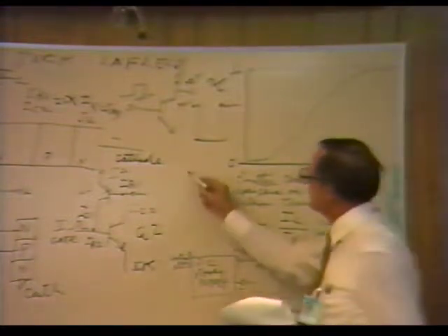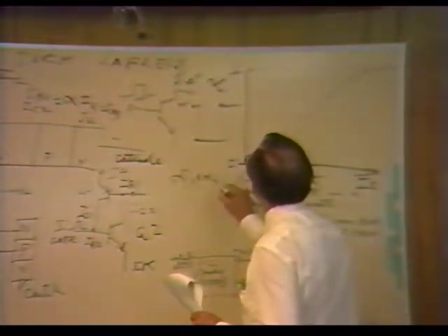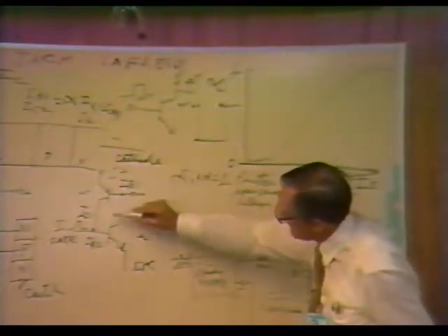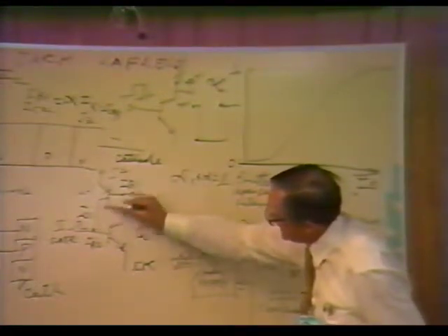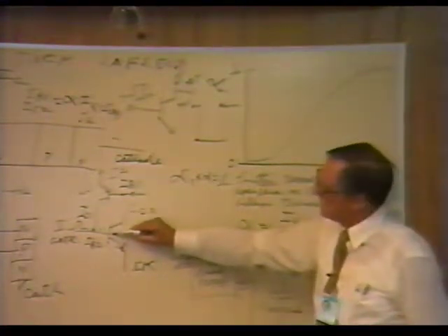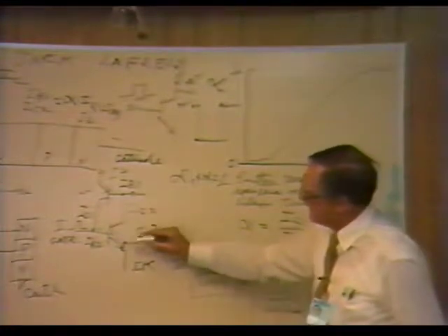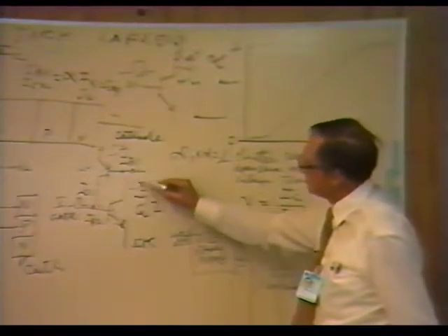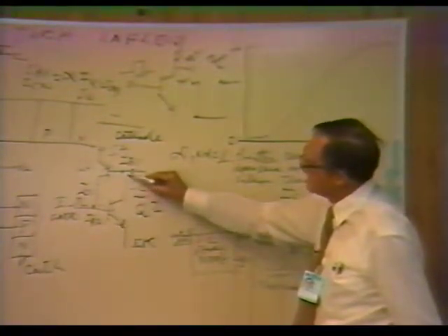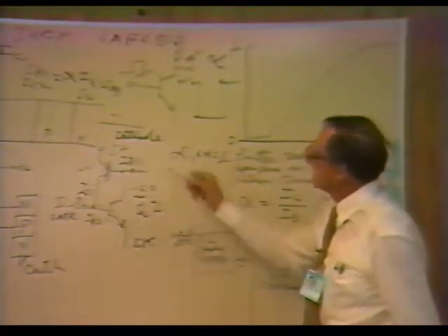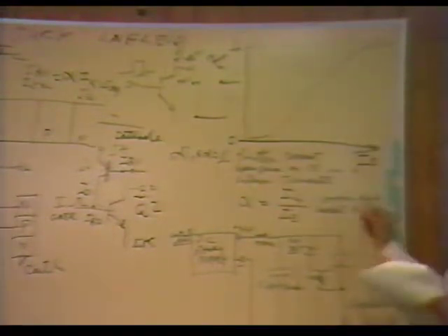And what we're saying is, if alpha 1 plus alpha 2 comes close to 1, then if the current in transistor Q1 is strong enough to keep Q2 in SAT, and the collector current IC2 is strong enough to keep the base of Q1 on and keep this transistor in SAT, as long as the alphas are close to unity, that device will turn on and be a very low current path.